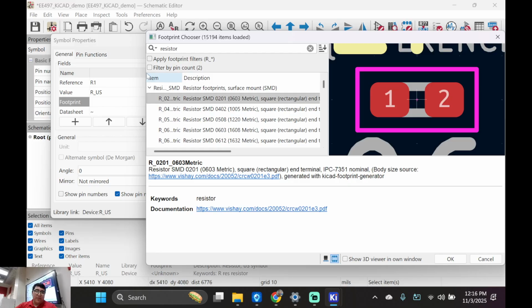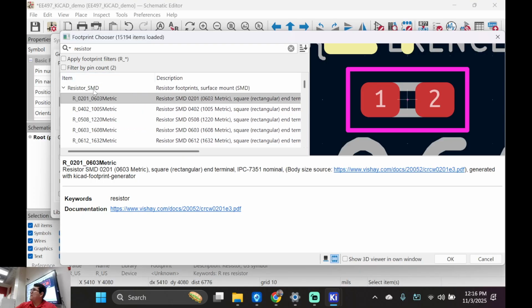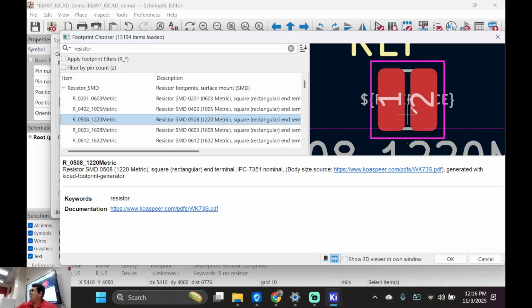So it'll give you a few things. Let me just do SMD, right? If you need an SMD, this is where you'd go if you're doing very tiny designs. There's a couple of codes, and all the SMD resistors are always based on codes. So 0201, 0402, and this is basically the layout size. So this is what they'll look like. Let me see if I can show you.